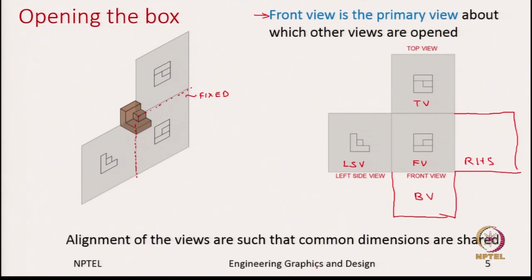And the last one is the rear view. Rear view you can either place to the left of the left side view or to the right of the right side view, but we normally place it next to the left side view. So, let me show it here. Rear view. This is how we open the box such that now all the views are in a single plane.